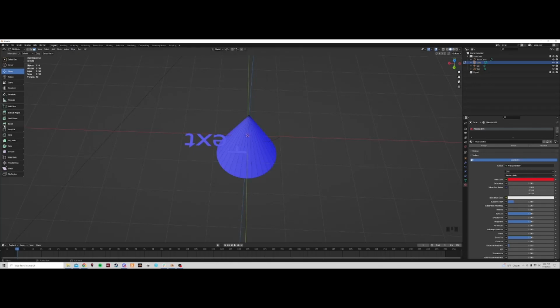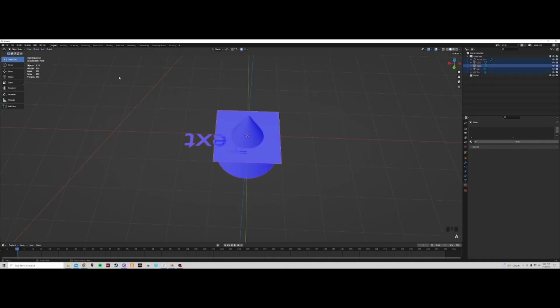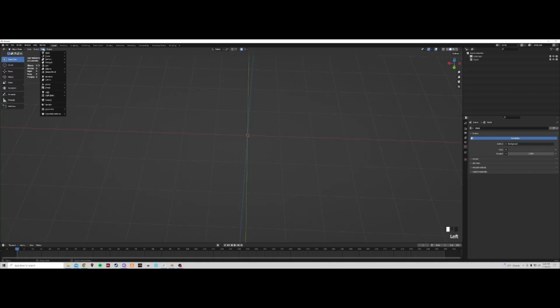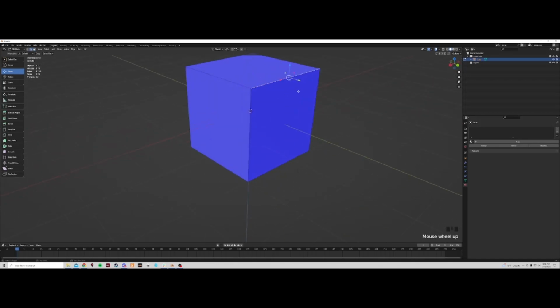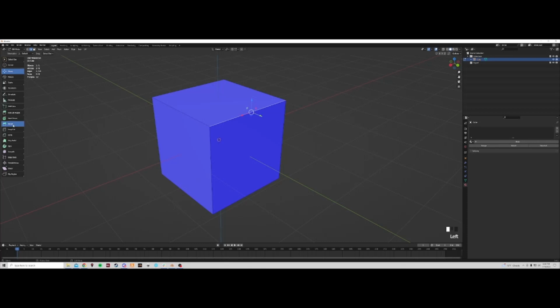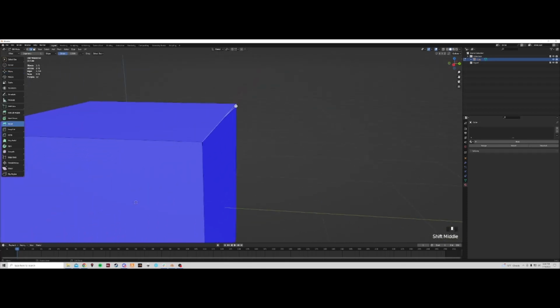Now, you can do things like bevel. I'm going to do this on a box. Much easier to see what's going on, not a plane. Cube. Okay. So if I take an edge, one single edge right here, and I go to the bevel tool, if I drag this little circle here, you will see that the edge splits into two edges.